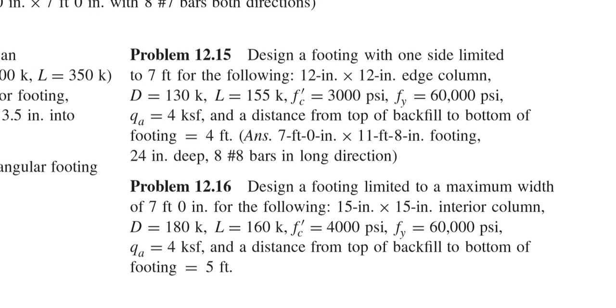Now, the problem did not tell us whether it is a rectangular footing or a square footing. Typically, when you design a footing, you do not know whether it is square or rectangular. At the beginning, we will always try to make it square because square footing is better. It is stable, equally both ways. So we do not like rectangular footing. But sometimes due to the boundary line or availability of the land, we cannot provide a square footing. Even for combined footing, sometimes we may need to provide several footings together.